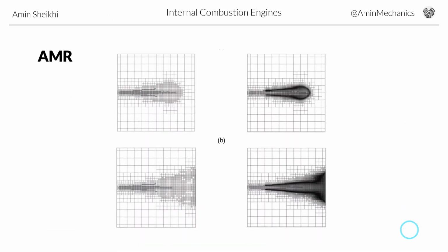Also, we can use adaptive mesh refinement or AMR to automatically refine the grid based on fluctuating and moving conditions such as temperature or velocity. This feature may be used to obtain a refined grid in flow regions of interest, allowing complex phenomena such as flame propagation or high velocity flow without unnecessarily slowing the simulation with a globally refined grid. This figure shows post-processing of a grid generated by AMR for a spray bomb case. In this case, the velocity is allowed to embed 3 levels, while the temperature is allowed to embed only 2 levels, which significantly reduces the computational time as compared to a simulation with fixed embedding or with a finer base